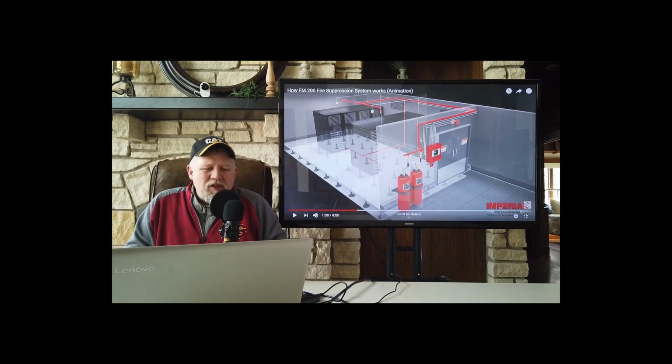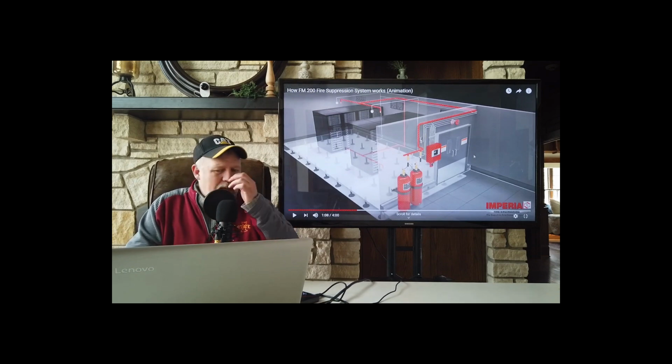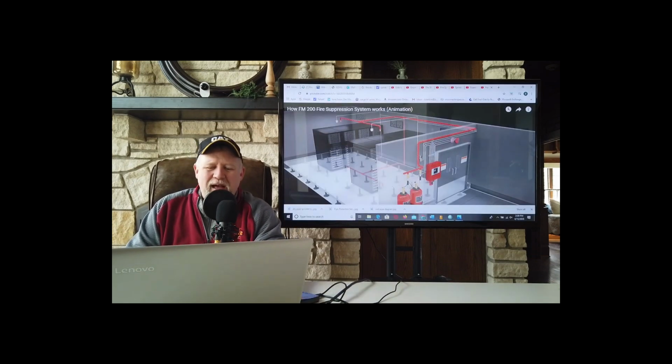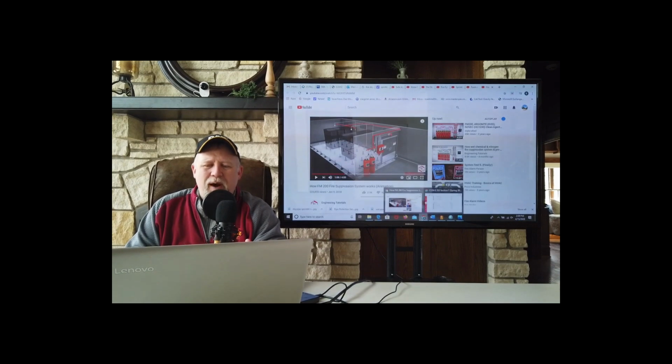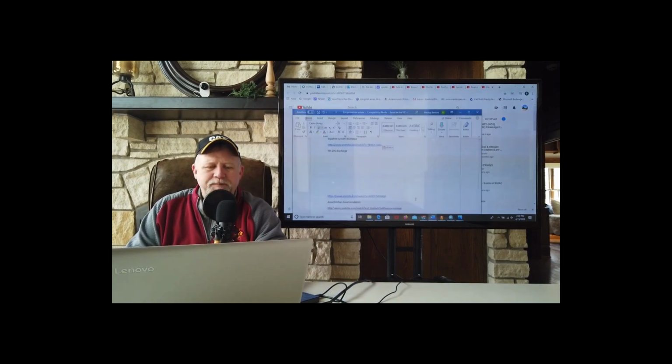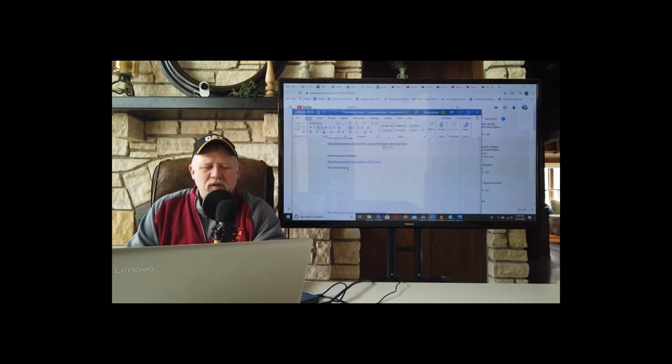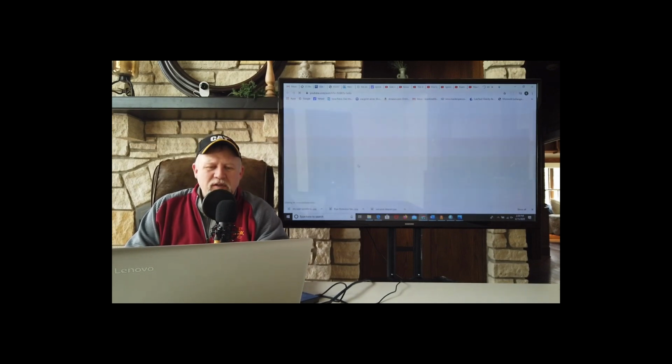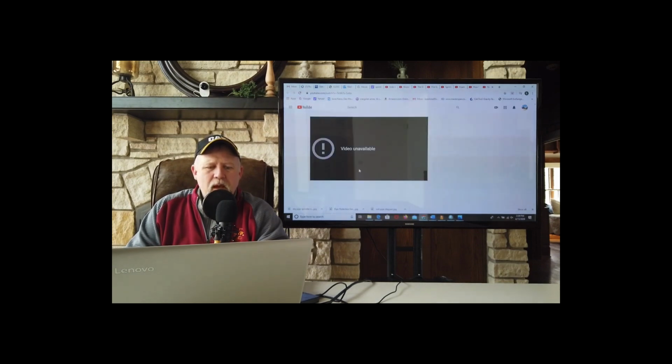So the fire suppression system, while expensive, is a fraction of the value of the intellectual property and computers that are within that room. Now, FM200 is commonly used as an extinguishing agent for computers and servers. There's also another agent that's not used just for computers, but is also used for priceless antiques.